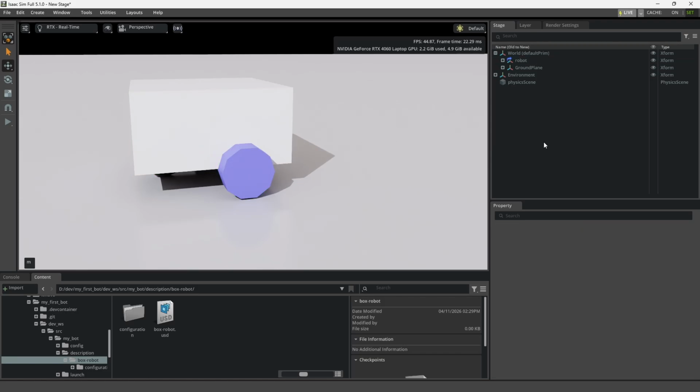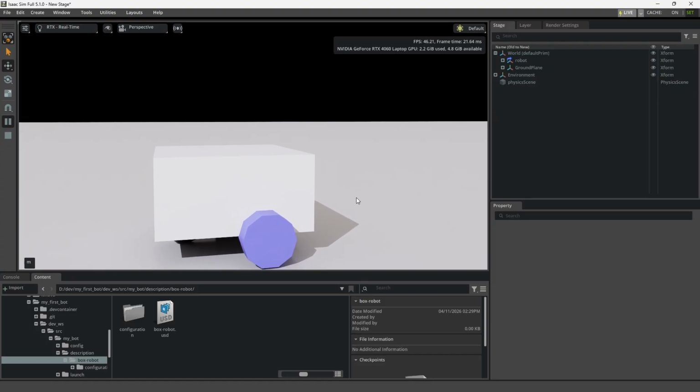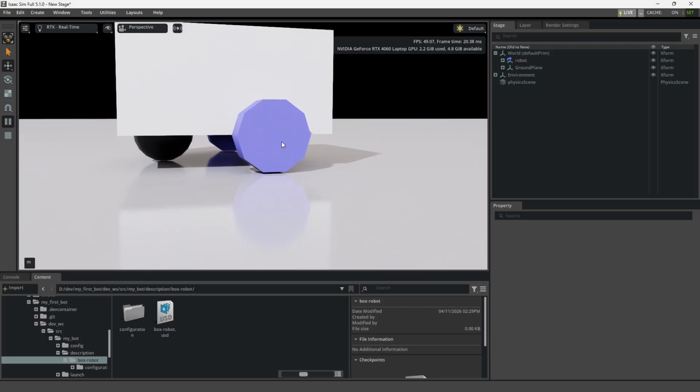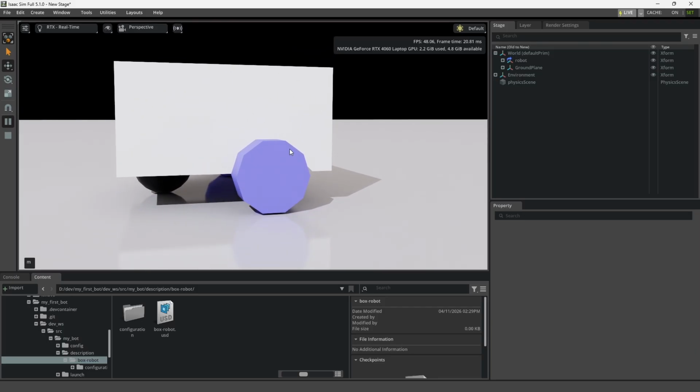And what will happen here if we push the simulation play button, it's not going to do anything other than maybe just drop a fuzz of an inch down to the ground, basically. You're going to notice that the wheels are really rough and it doesn't go anywhere. That's okay, because what I want to explain is that what happens with the wheels is that my original ROS robot had a primitive cylinder in it, and when we imported that, it created a low poly tessellation mesh, which basically optimizes the visual side of this thing.